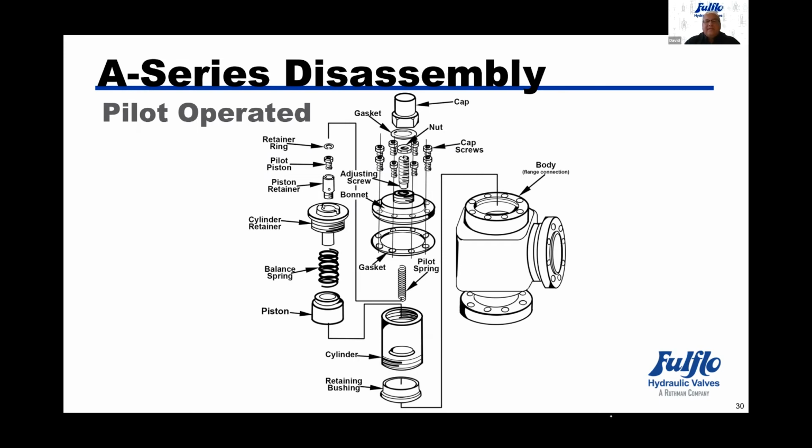When the main piston opens up, that's the set pressure at which the valve is actually going to control pressure. Everything before that we call internal leakage, or just the nature of the design of the valve. As the main piston opens, it's going to regulate the pressure. As the pressure drops back down, the main piston would close and the pilot piston would close as well. So there's two valves inside of one housing.